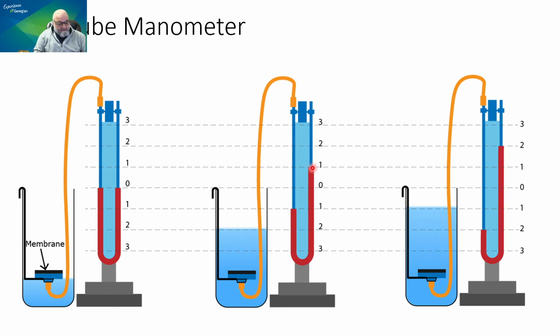All right, so in this case I'm reading 2 inches of water column, and similarly I added whatever substance that is, and I started reading 4 inches of water column. So as long as you're reading 1 to, I would say, 5 inches of water column, a U-tube manometer is one of the best measuring devices that there are. So this concludes our air pressure measurements. If you have any questions, you can ask now, or I'm just going to continue with the volumetric airflow.